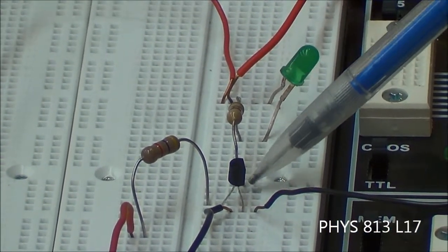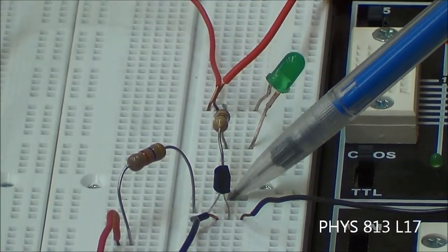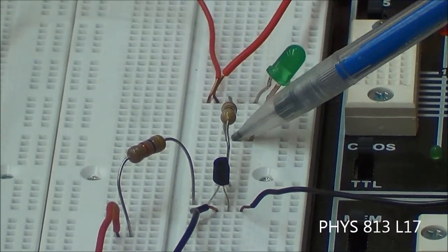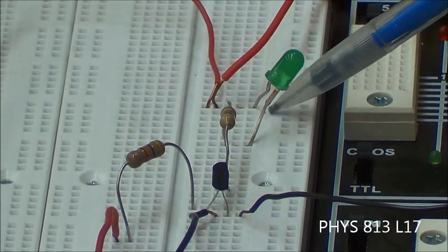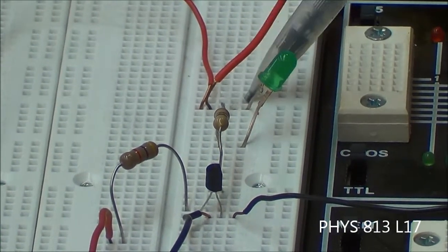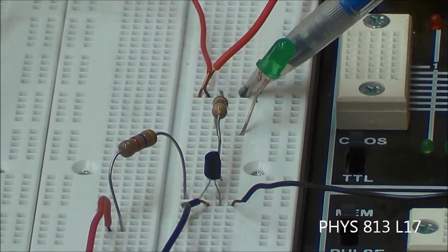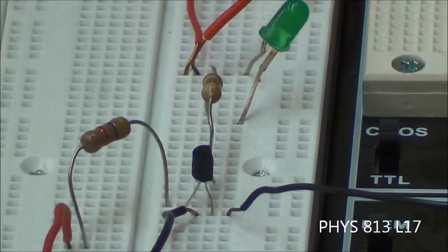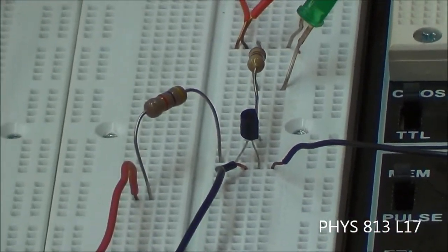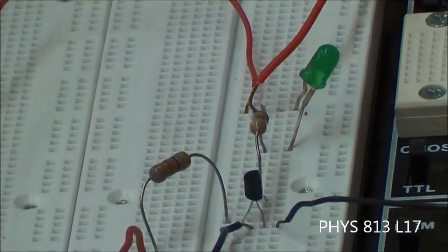So it goes in the same row as the collector leg of the transistor. And then you have it on up here somewhere. And then you have the LED, which I'll say more about in a minute. And then the other end of the LED goes up here. And then it needs to go to the positive 5 volt fixed. So notice that this red terminal says plus 5 volts.